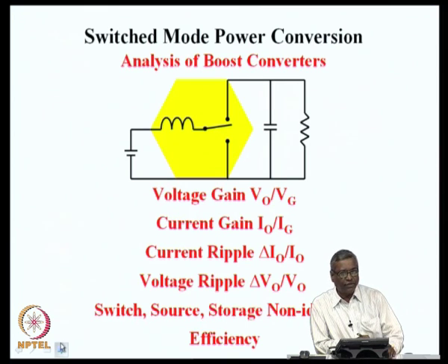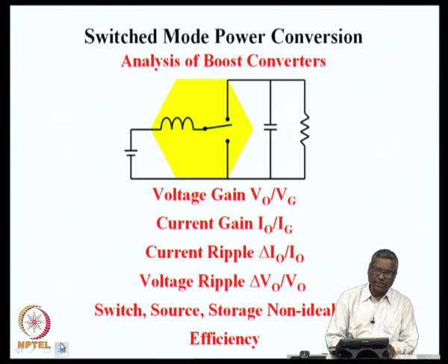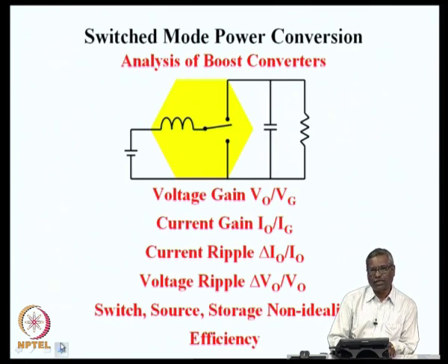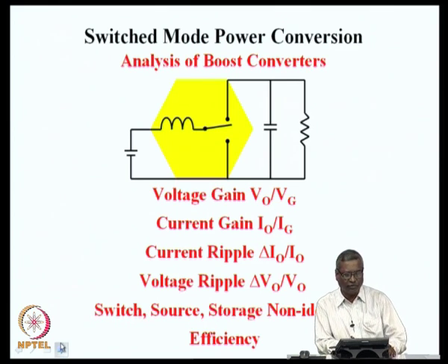But because we are using switches in the converter, power is being drawn intermittently and it is delivered to the load intermittently, and the purpose of the inductance and the capacitor is to smoothen the power flow. So, on account of that, we will get what we want, namely steady state average output voltage and steady state average output current, but on all these quantities, on the output voltage V naught as well as the current I naught, we will have a switching ripple.